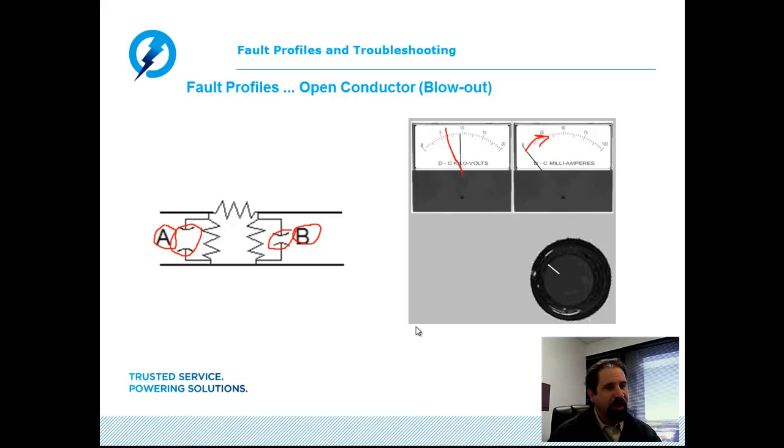Rather than fighting the problem, most times it would be very beneficial, if you have access to the other end of the cable or the load side of the circuit, to simply move the equipment, connect onto the load side of the circuit, and shoot back. Again, chances are on the load side of the circuit the gap may be much more reasonable and will allow you to get much better thumping conditions.